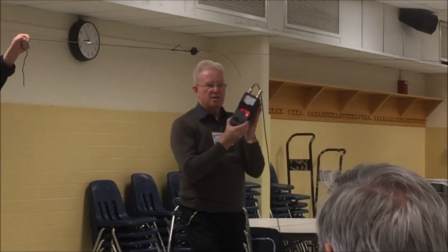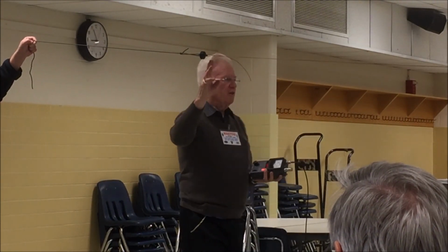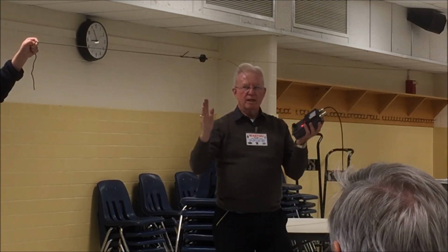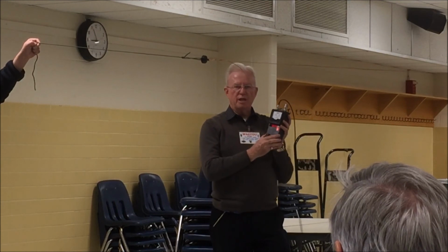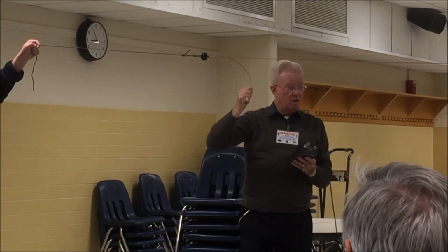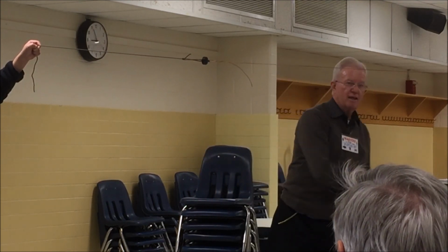So anyway, let's just say if we weren't resonant, I can get this thing out in the forest or at my house, and I can get this almost to the hertz. This has a digital readout, guys. And I go down here and snip, go down there and snip, and just keep getting less and less. Pretty soon you get right on your resonant frequency. I have my antenna lowered at home. And then what I'm going to do is wrap this and solder it, unlike Terry.